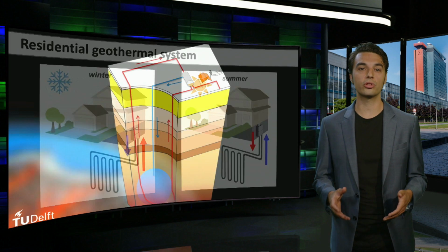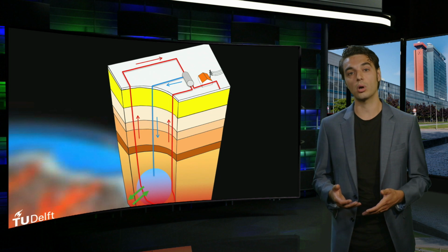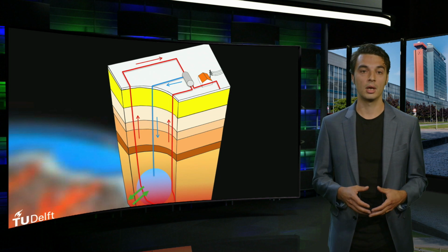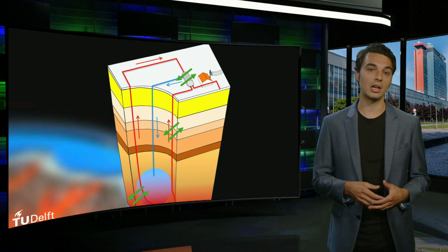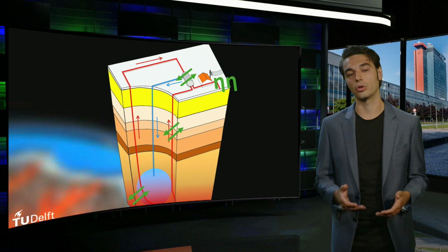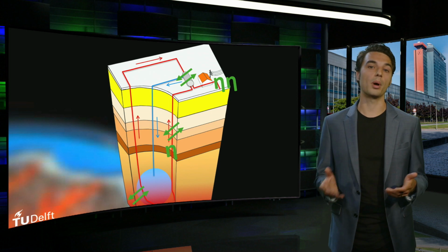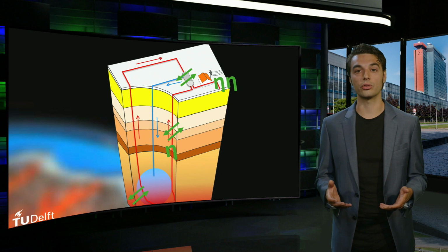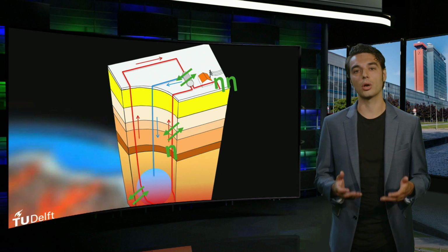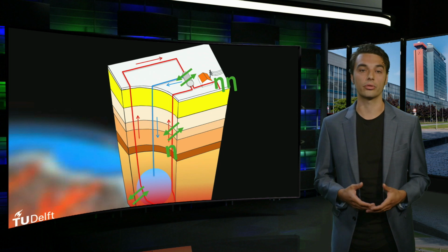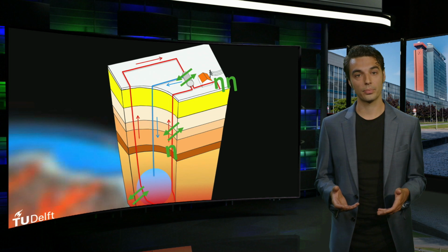Losses in a geothermal system are mainly the result of heat exchange efficiencies between the water reservoir and the rock beneath the crust. Apart from that, there is a heat loss in the pipes and in the heat exchanger and conversion losses in the turbine and generator. Additionally, since the water needs to be pumped up, there are electrical pumping losses due to friction in the pipes. For economic feasibility, the hot water reservoir should be close to the surface so that the frictional and thermal losses in the pipes are minimal.